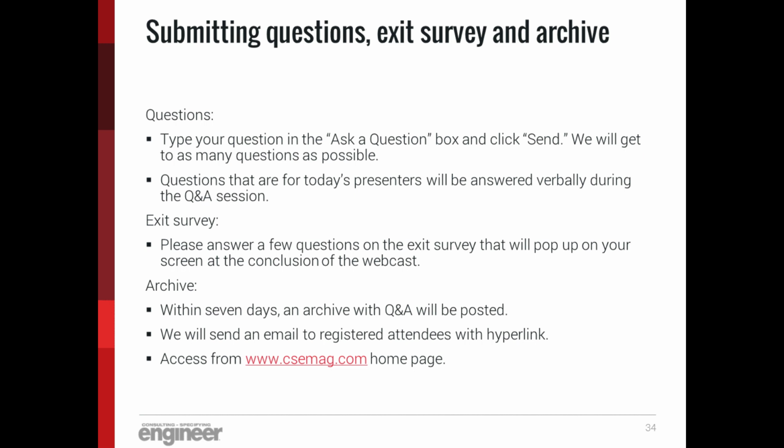Yes, thanks, Amara. Now, we want to be careful because when we're doing ground fault, yes, that's a requirement on the normal side. And if we're talking healthcare facilities, then we're looking at selective coordination requirements. So that means we're going to have the main and the branches. Now, NFPA also explains, and NEC does, that that's not two in series. It's not two main breakers in series. It's the main and the branches because the intent is selective coordination. We want to maintain selectivity so a ground fault on a branch doesn't take out the main.